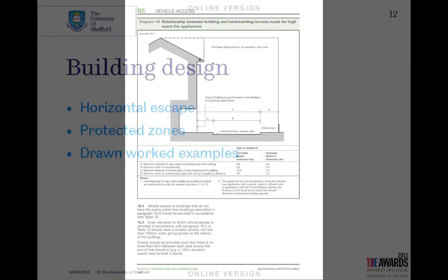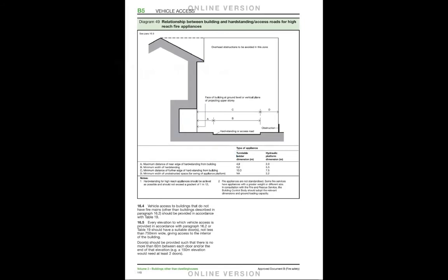If you couldn't comply with any of this, you'd be into more complex fire engineering. Okay. I've not gone into there's more detail than this. There's details about fire hydrant provision. There's details about getting the fire hoses inside the building. But I think that's, dry risers, wet risers, but I think that's a bit beyond what you need to think about.